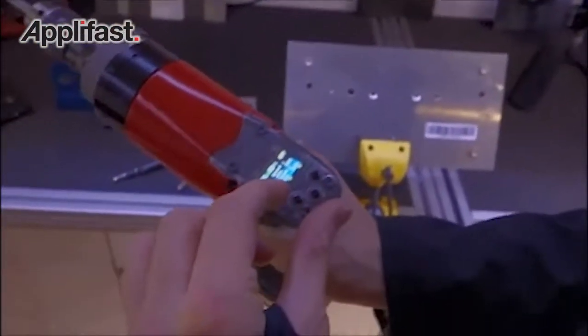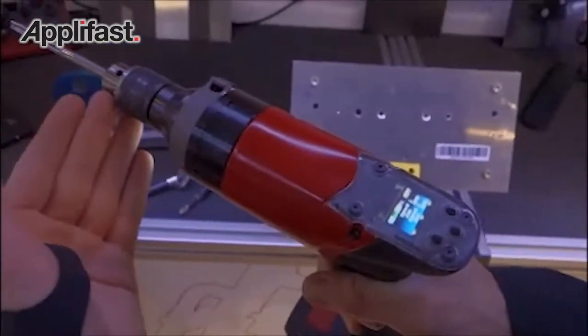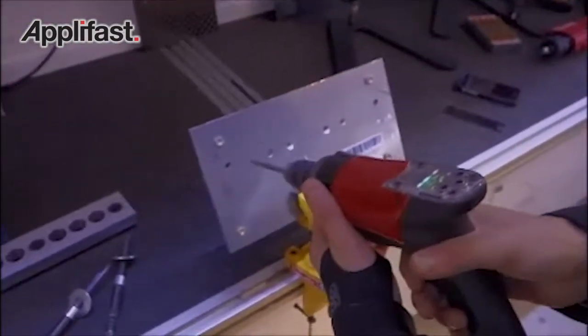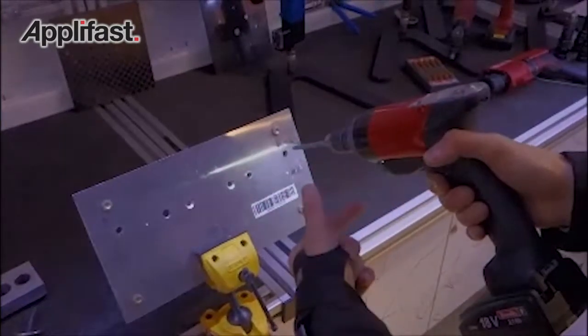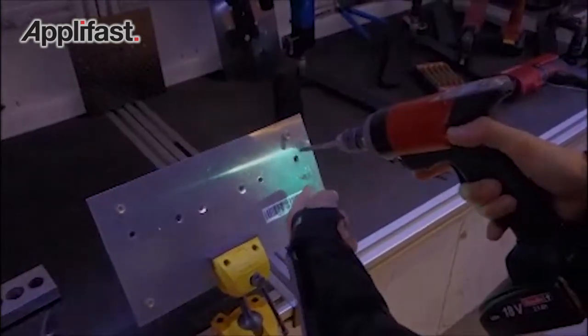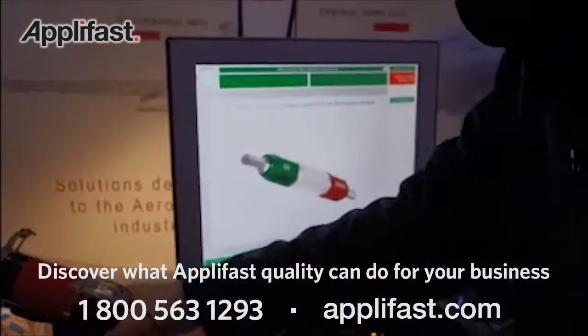So I select my second head, I connect, and as you see with the same tool, now we are reaming at a speed of 600 RPM. So the motor directly recognizes the head. So I'll do my reaming. Same thing, following the sequence. And as you see, there's a reporting. When the operation is done correctly, then you will have a green light directly on the surface.